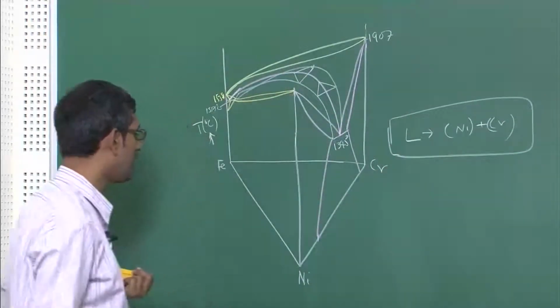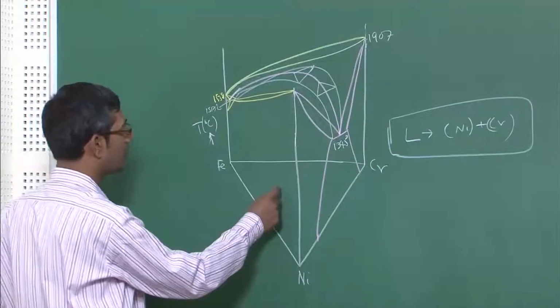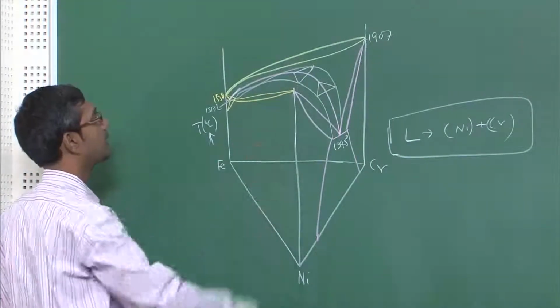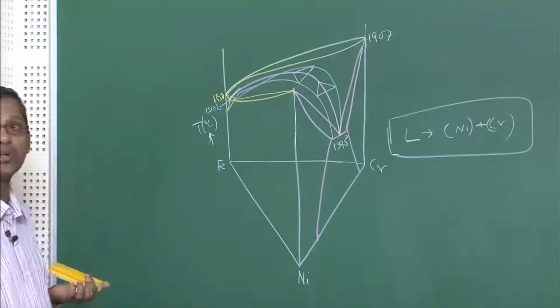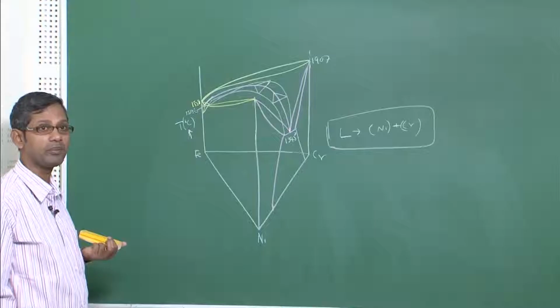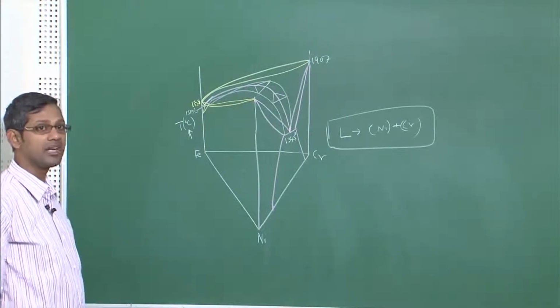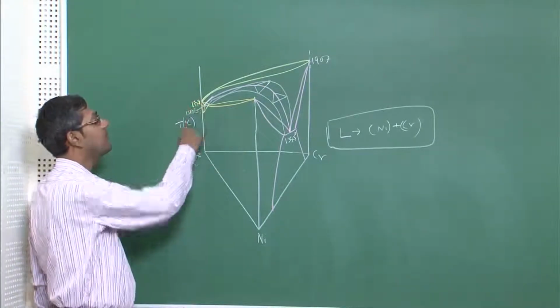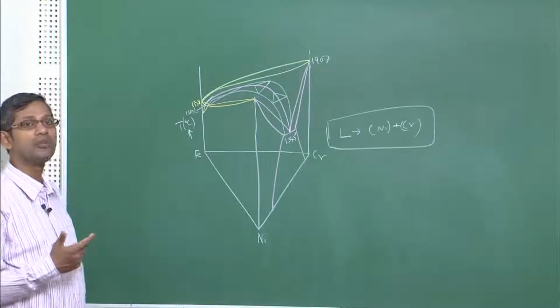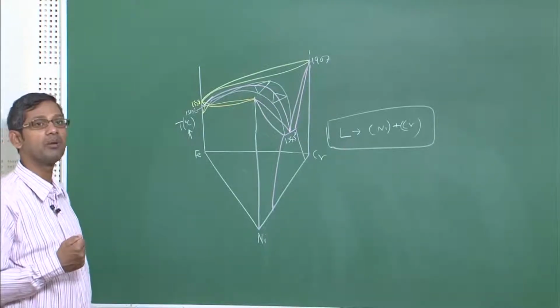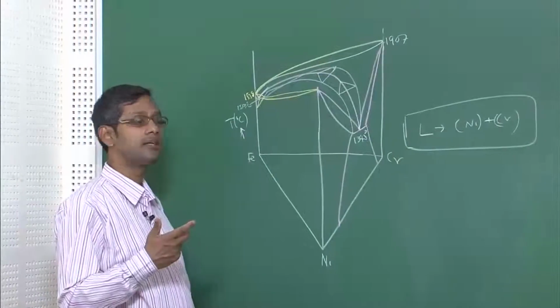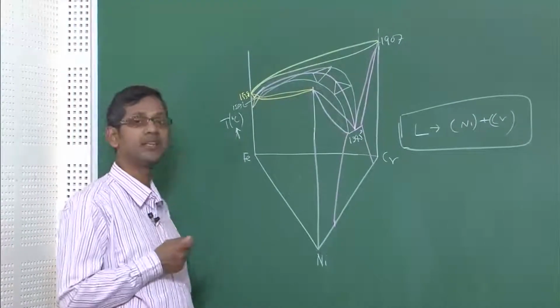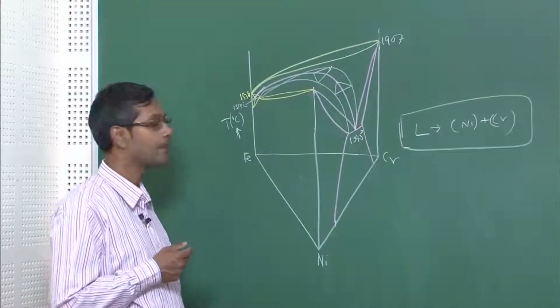The stainless steels actually are iron rich compounds, so they lie somewhere there actually. So, in most of the cases they undergo the peritectic reaction, that is what you should remember. But there are different types of stainless steel. If the stainless steel contains a little bit higher amount of nickel, then the peritectic reaction usually happens. In fact, that is why for most stainless steel the basic problem is welding. In case of welding, the stainless steel undergoes this peritectic reaction and forms a lot of cracks.